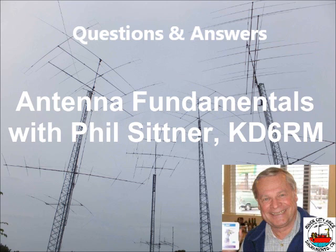The N2PK has a dynamic range. Are you ready for this? 140 dB dynamic range. Wow. Which is just right on the edge of how good a Hewlett-Packard or an Anritsu or many of those guys are. 140 deep, which, again, we saw how those numbers range. That's 1 to 10 to the minus 14.